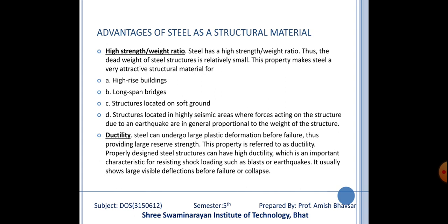In that case, if it is an RCC structure, it will collapse for a smaller deflection. But in steel structure, due to high ductility, it can deflect more as compared to RCC. That's why ductility is most important and it plays a key role in buildings.